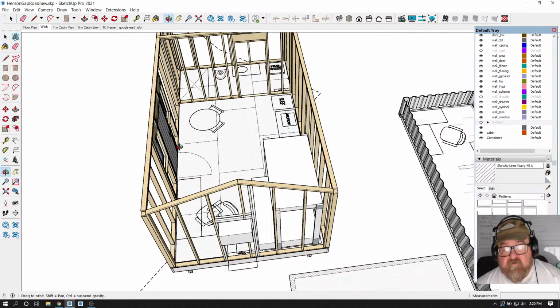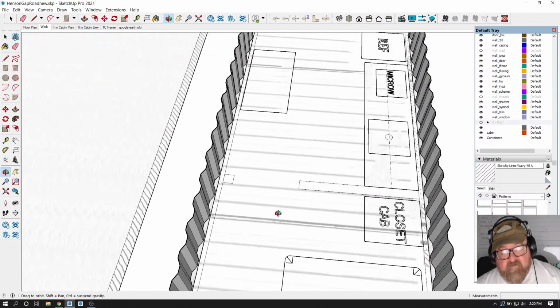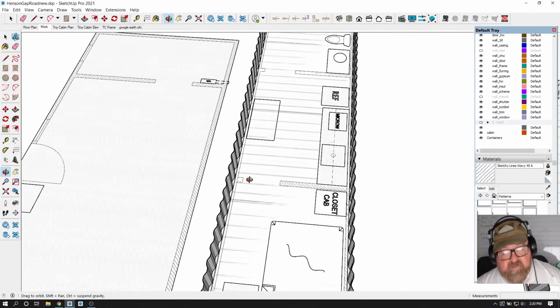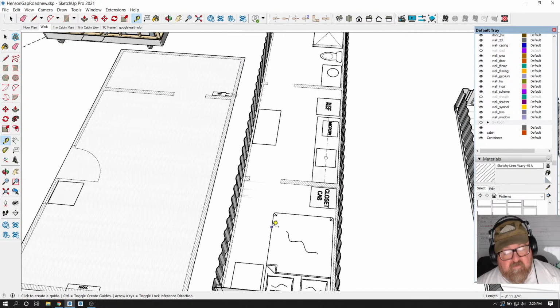Okay, so now you see this. You see the tight spaces. This is less than 3 feet. Well, when we're designing hallways, or what we call circulation, we always want like 3 feet. So that's only 32 inches, and this is just a full-size bed. I'm a big guy, this is just for me, but for 2 people, you'd probably want a queen-size bed, which is going to push this table all the way over to the end.